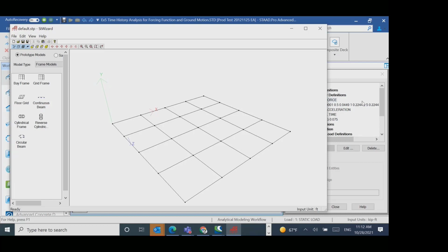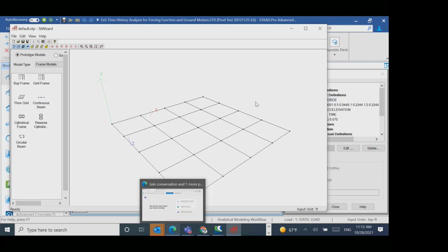You export to STAAD and you define the load, and the main difference is you need to define the lifting points in the correct position. This is one of the important parts. Remember, the steps are 7. Geometry, the first one. The second, specification. Of course, it's not a big deal. You define the specification of the beams.